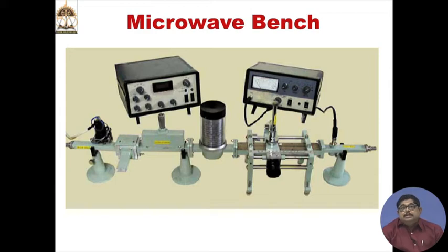So, that is why there is a waveguide with a slot cut at the central portion, through which a probe is inserted, and that probe, which is basically a point contact diode probe, is connected to a meter. This is a new thing, called a VSWR meter. So, there are two boxes you are seeing. The right one is the meter where you see various parameters, particularly VSWR, which will come next, and the left side is the power supply for that klystron source.